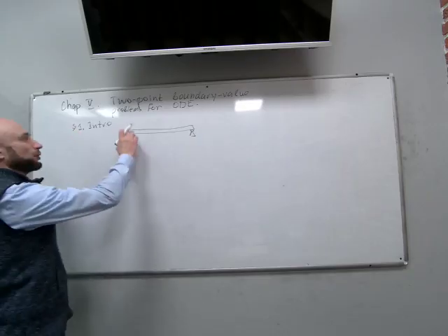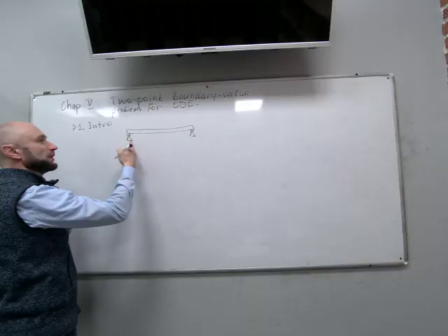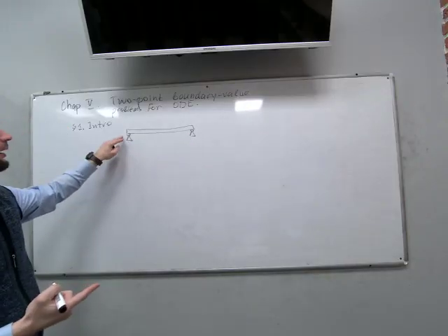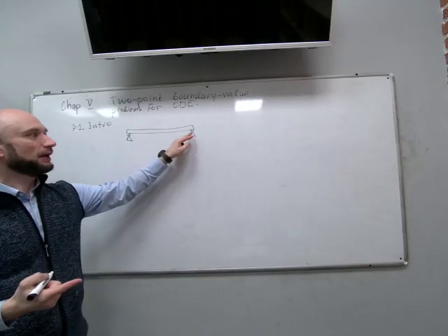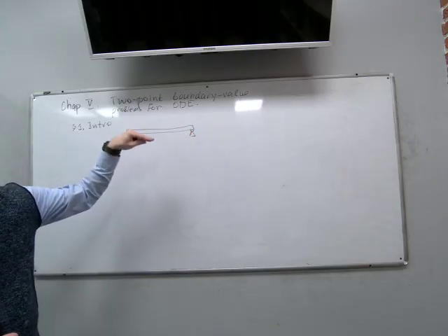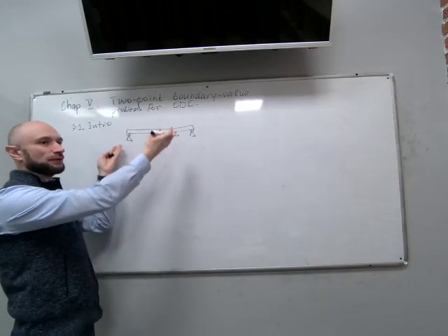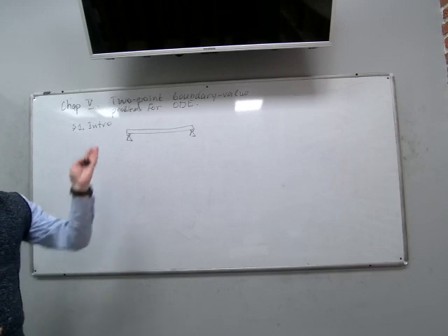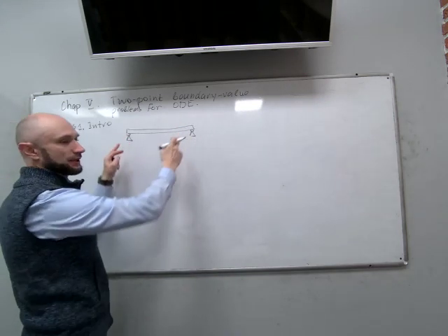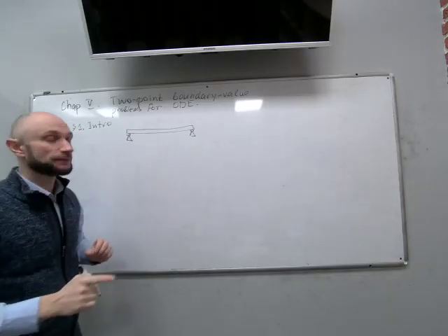But this problem will be simplified or idealized. So we have a beam, a single beam, on 2 supports that allow for free rotation. They only provide support from the bottom and prevent beam from falling down. And also, at these points, the beam is fixed from the horizontal movement.